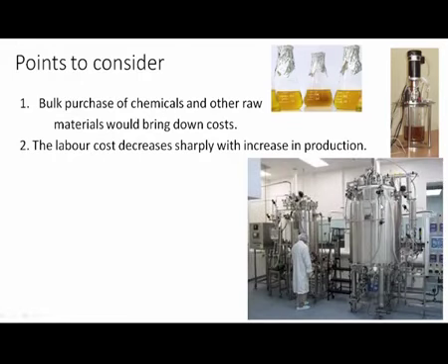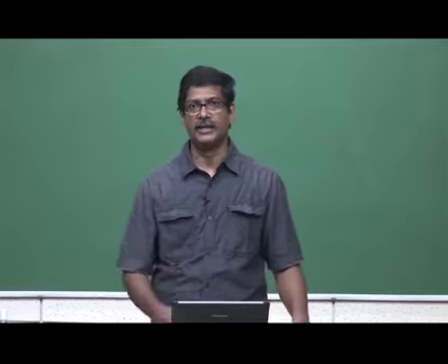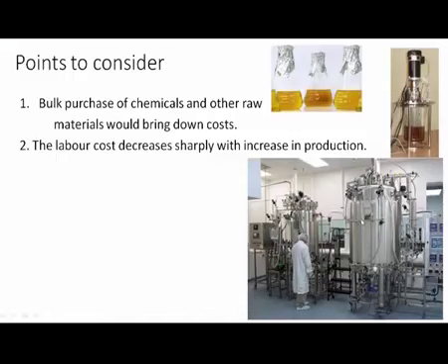These are still smaller fermenters, of about 500 liters or 1000 liters production capacity, but large pharmaceutical companies have huge vessels with multiple probes, one maintaining the pH, another the aeration, another stirring the entire culture so that it is well aerated and goes around in all corners of the vessel. All those parameters are maintained. There is a feed of the culture which continuously provides food supplements to the growing organisms, and all those parameters are maintained through some modules.